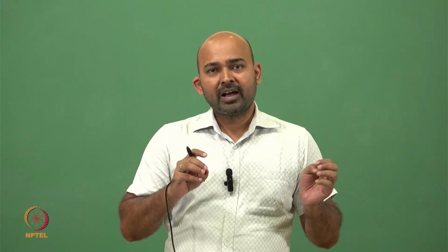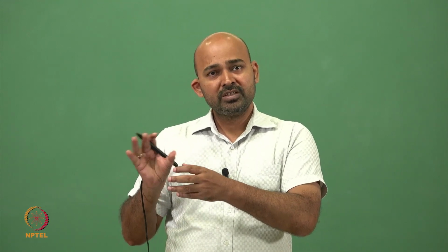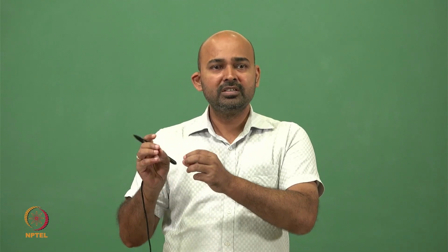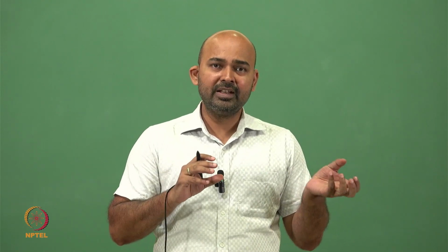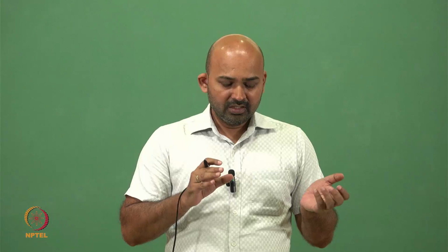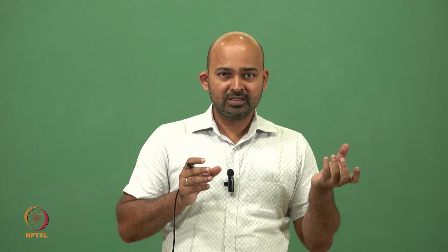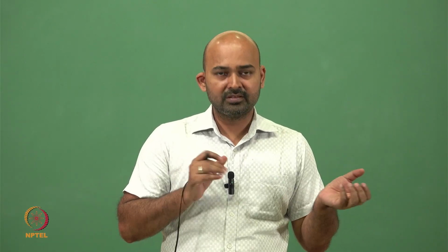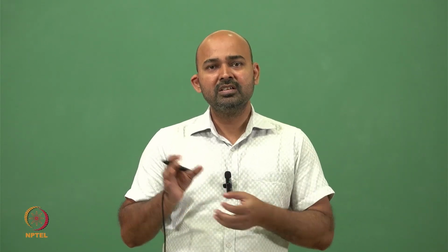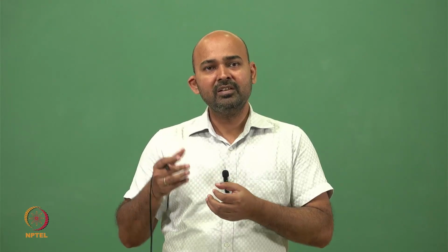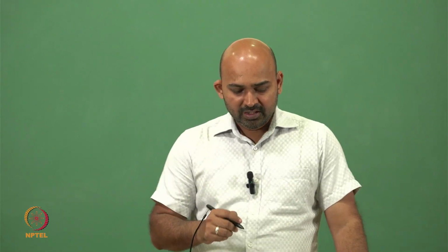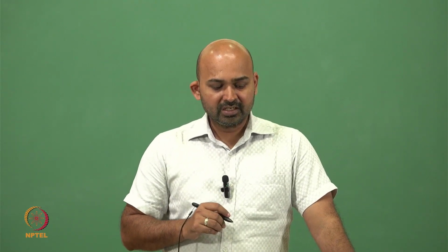If we connect this stage directly to a microcontroller which is running at 5 volts, this 5 volts can interfere with or can damage this sensor directly. So the signal conditioning unit provides isolation so that the sensor can act efficiently at low voltages, and the microcontroller sees a signal which is 0 to 5 volts. So these are some of the functions of the signal conditioning unit.